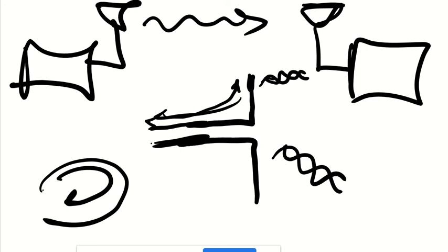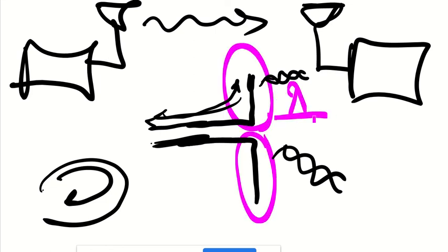And it's all because of this transmission line that I just told you about, and because of the standing waves, and because of the impedance mismatch. That's why you have the waves going forward and the waves going backward. So if I'm careful with the length here, which is usually lambda over 4, then I have standing waves, which result in transmission of electromagnetic waves because of the standing waves created inside. So whatever you're learning is all connected and will make sense when you look at the antenna.